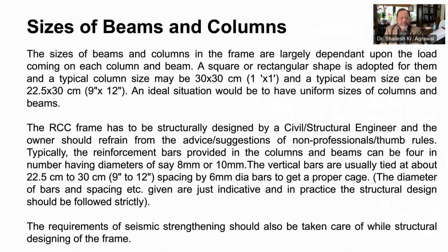Again, these diameters and spacings are based on thumb rules and indicative only. The owners are advised to refrain from these thumb rules and seek advice from civil or structural engineer. One of the important things is the requirement of seismic strengthening if location falls in seismic zone, and accordingly structural design and construction should incorporate the same while doing construction with RCC frame construction.